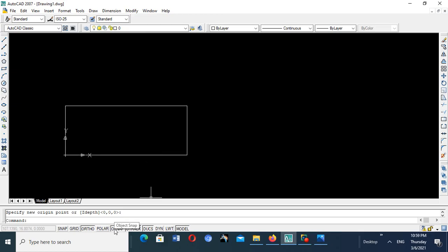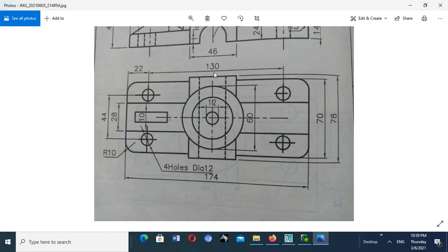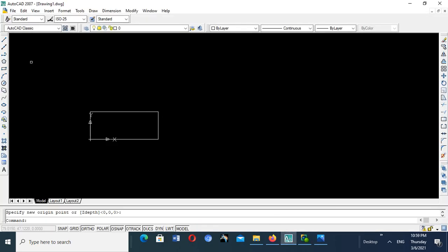Alright. Then I want to draw the middle lines so that I can start drawing this rectangle. I want to draw this vertical center line, and I also want to draw this horizontal center line. So I come to my AutoCAD, I pick line, then this is the midpoint of that rectangle on that axis. I've come and selected it here.